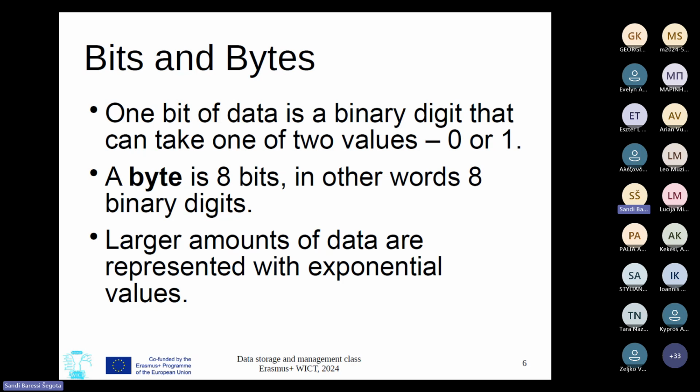So 0, for example, if you're using a 5 volt system, 0 will be everything from 0 to 2 volts, and 1 will be anything from 3 to 5 volts, with the values in between being undetermined. We'll say, okay, we aren't sure here because maybe we have some voltage loss or some extra voltage coming in here that we don't want.